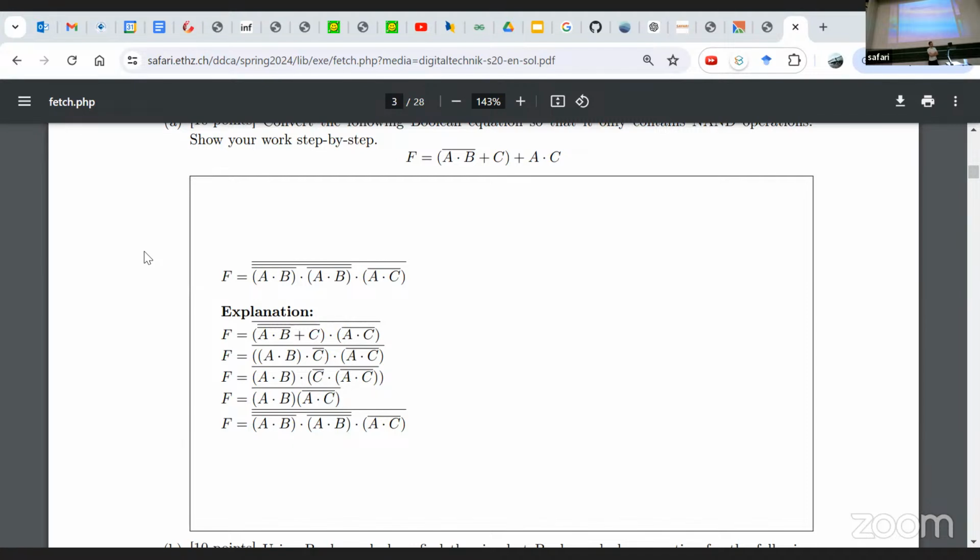Look, there are only two timing constraints, right? You have setup time and hold time. For the setup time, for how much time I need, for that constraint, you need the longest possible case of everything. And then you have a hold time constraint, where the problem is that signals can propagate faster. What happens if something comes very, very fast? You need to know both of these things, because questions can come up and we'll assume that you know both issues.